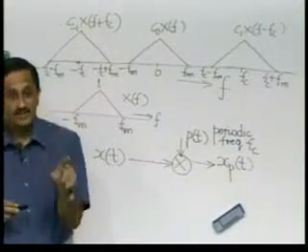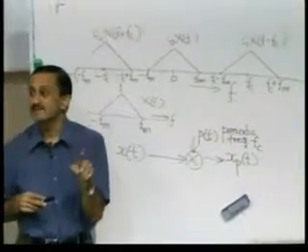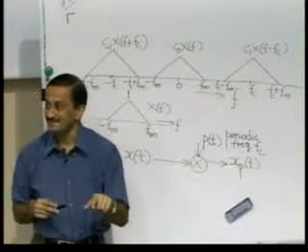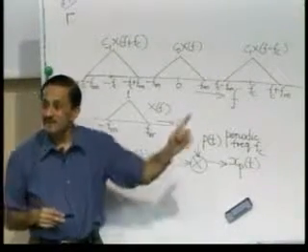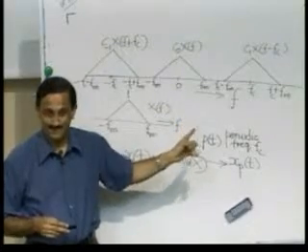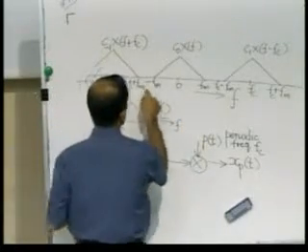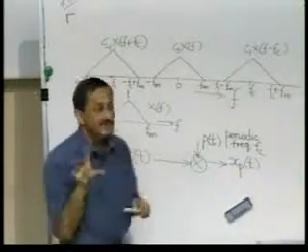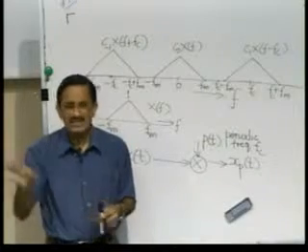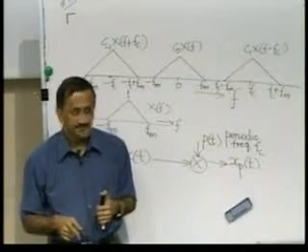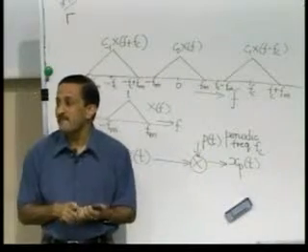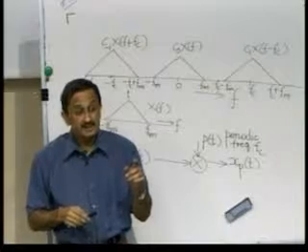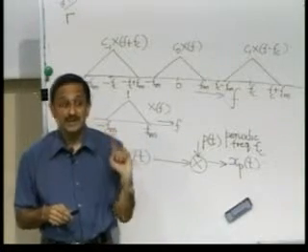Now, if our intention were to replicate the original waveform x(t), we would have put a low pass filter with a cutoff of Fc by 2, right. So, had we put a filter with a cutoff of Fc by 2, we would have got back C0 times X(f) or some multiple of X(f), and from that we could have reconstructed the waveform x(t). But now we can exploit the phenomenon of aliasing.